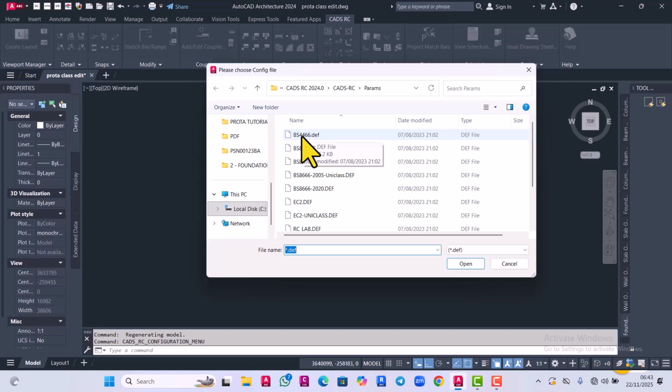When you come to a slab, we have some bars that are straight. Maybe when it's found inside the building, the bars will be straight. But when it's found at the edges, you have to return, you have to anchor that bar, and that automatically is a different shape. Your links are also a different shape from a straight bar.